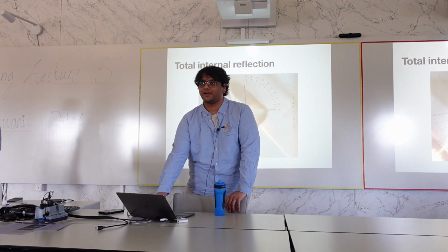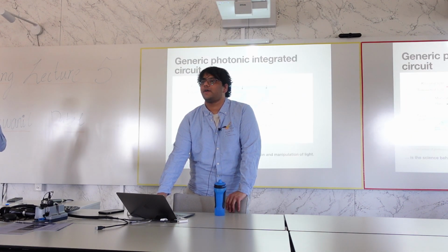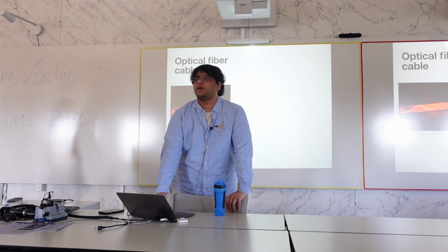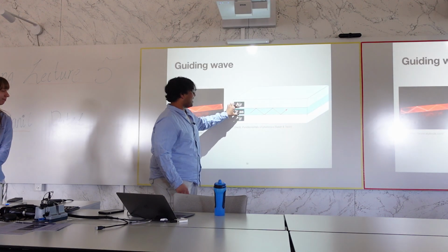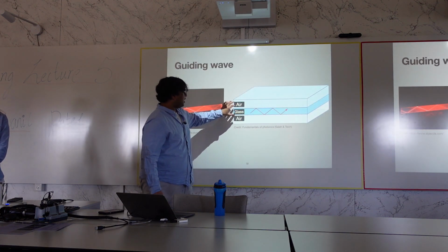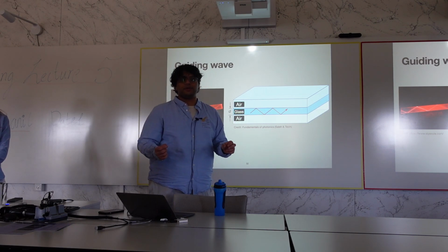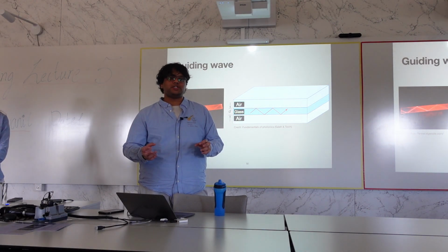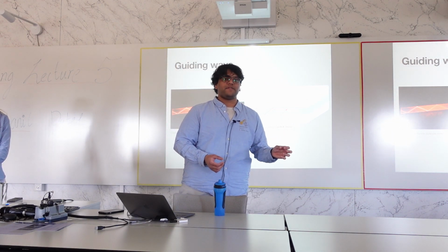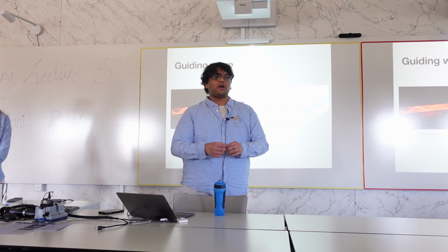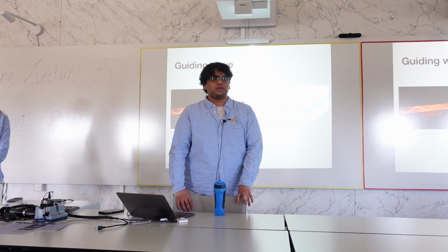No. So that's again a very good question. The way this light gets confined into the glass is dependent on the wavelength and hence the material around it. These are narrowband instruments. So let's say if you optimize your chips for 1500 nanometers, then it would be fine for probably 1500 to 1600, but not more than that. So probably a full width half-max of like 100 nanometers, something like that.